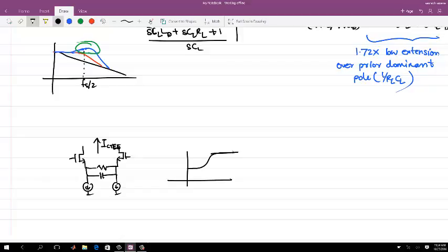Effectively, I can change the zero location. It is still not limiting your peaking frequency. And if you start using only simple RL, with the inductor you can get an extension, but that is one other thing. Inductors depend on the area also. Whether you will use the inductor or not, that's a question. Or if you want to extend more, what will you do?